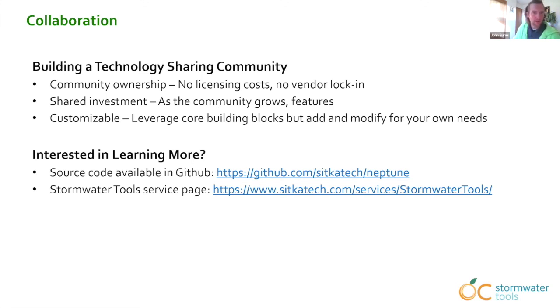I was late into the meeting, but do you differentiate between condition assessment and maintenance priority rating? In standard asset management protocols, the condition score is based on structural physical deterioration and routine maintenance needs, such as trash, vegetation, sediment accumulation, that can be assessed with maintenance crews. Condition scores are more construction related, such as concrete pipe replacement, stabilization, major basin reconstruction.